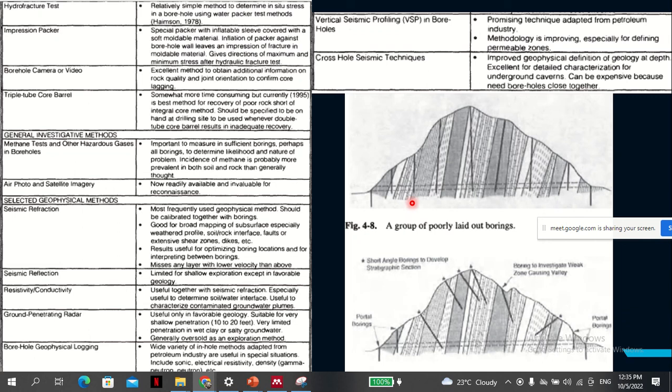So in summary, in the rock classification system, you have to consider the fact that joints have a very strong influence on the behavior. We had initially the rock quality designation RQD, then the total core recovery, then the Bieniawski RMR system, which we've described rates a rock from 0 to 100, and now we have the Q system proposed by Barton, which gives values from 0.01 to 1000.